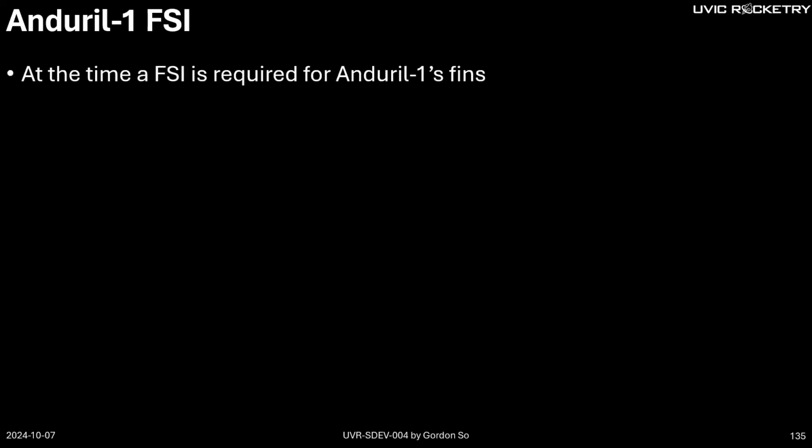This is mostly because we need an FSI for the fins that we have, and that's not something you can just get from estimation, because it's pretty difficult to know where the center of pressure is. So we do both things. We do a hand calculation of the fin lift, and we also do a CFD, just to compare the results.